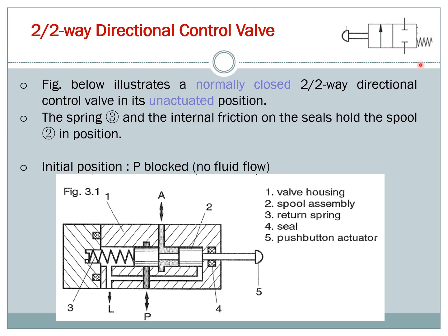The symbol is almost similar to pneumatic, but this is for hydraulic. Although the symbol looks the same, the connections differ: it won't have a connection from compressed air and exhaust. Instead, in hydraulics you will have connections from your pump, and the exhaust will be replaced with a tank. We will see later in the circuit.